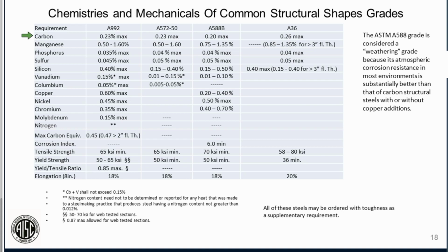So then we look at manganese next. That's a big one. It's a big addition. It's the biggest component of the alloying that we add in. If you look at A992, it goes from 0.50 to 1.60. I'd dare say you're definitely about 1% on most stuff. Same with A572 and A588, about 1%. A36, you don't have to achieve the same strength levels. The manganese is typically lower.